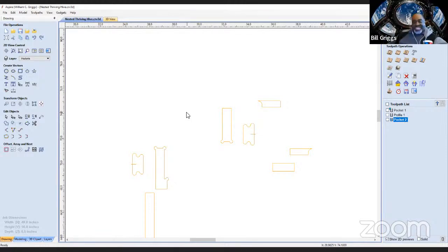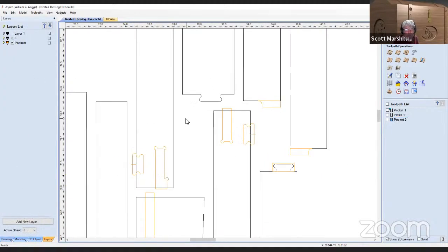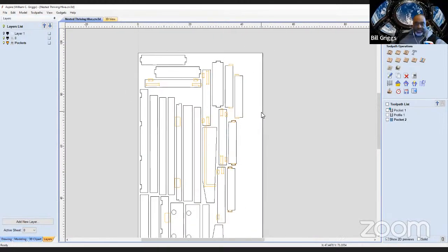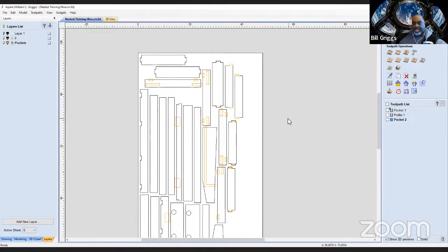But my point from all of this is that there is a way to get stuff out of Fusion into our programs. It's not a straight path, it's not a quick way, but it can be done. Have you tried exporting it as a vector PDF? I've done that before, but I don't find it as useful as DXF. DXF seems to work better in the programs I use. I've tried PDFs. It only worked well when I used TorchMate stuff. I'm going to delete this toolpath I just made so I don't have to worry about what was going on there.